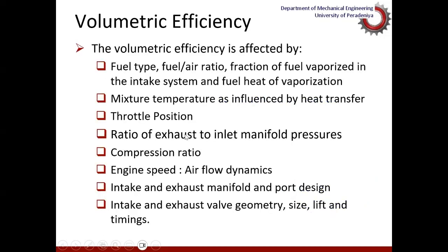So the volumetric efficiency is a key parameter in intake system design, and it is affected by the fuel ratio, fuel vaporization, mixture temperature, throttle position, ratio of inlet to exhaust manifold pressures, compression ratio, engine speed, the intake and exhaust port designs, as well as the valve geometries and things like that. Volumetric efficiency is affected by many parameters, and certain parameters are engine intake system design parameters, which could be taken into consideration when you design an intake system.